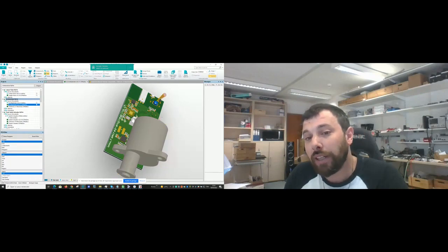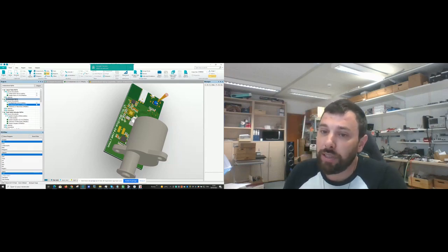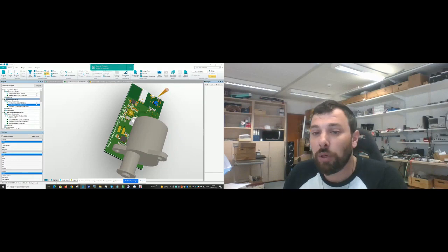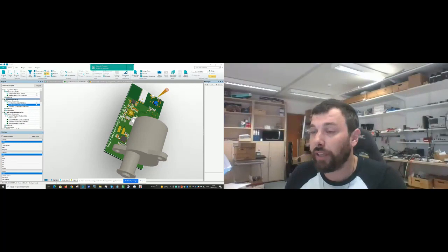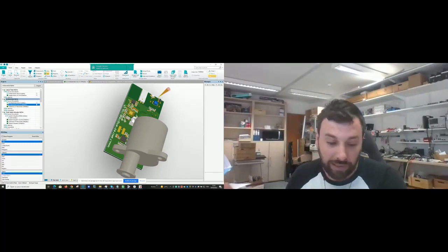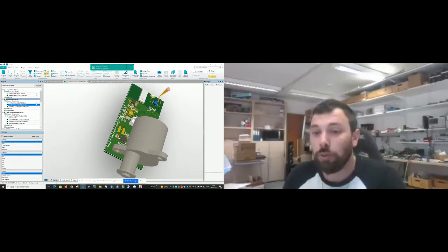We have the KNX push button. This push button is placed away from the PCB edge because of ESD. If someone near the device is charged with static electricity, it should not destroy the device. Here we have the KNX LED, and this is the antenna.